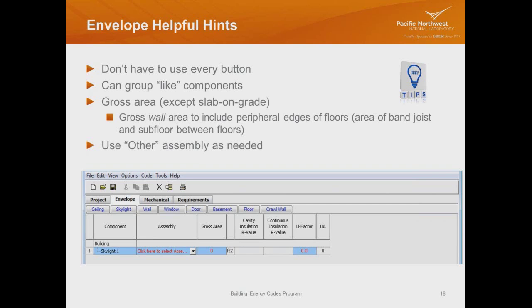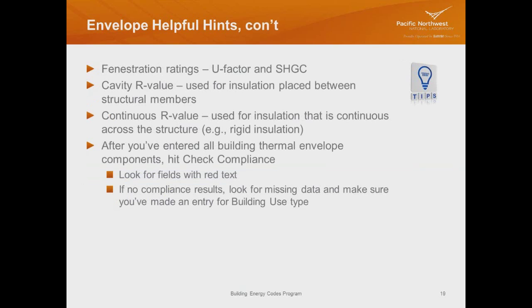So a complete calculation would be needed, total U factor. And then you would want to back up that calculation with your compliance report and your construction documents to the building official on how you calculated that U factor. So it's really important to take note of that one.